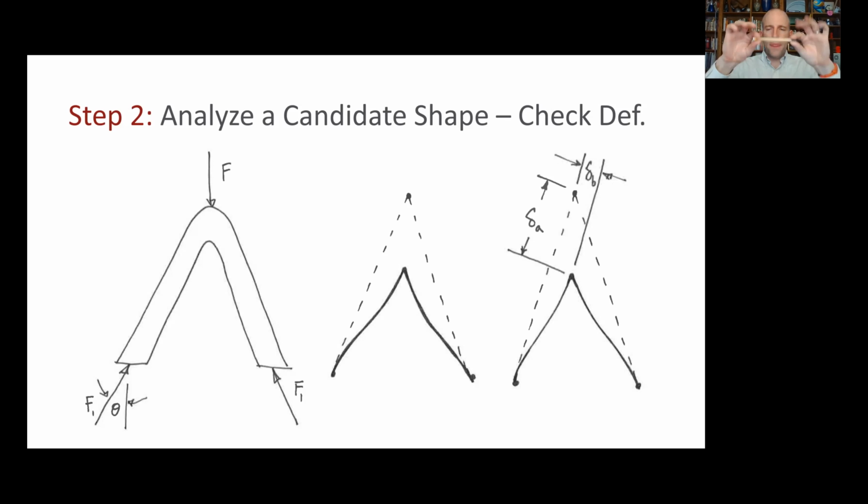And you can kind of prove this to yourself if you take a pen or pencil and push on it really hard, try to get it to shorten by 1/4 of an inch or centimeter. That is pretty hard to do. But if you bend it, you can pretty easily get it to deflect 1/4 of an inch or so. So both of those factors, smaller displacement and lower stiffness in bending, suggest that orthogonal force will be small compared to the axial force. So this is a reasonable assumption.